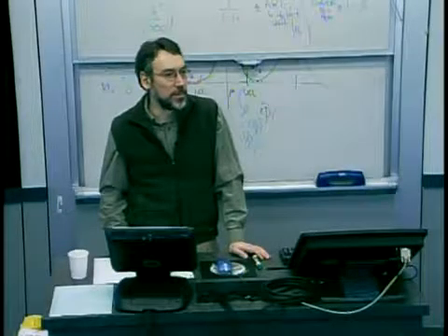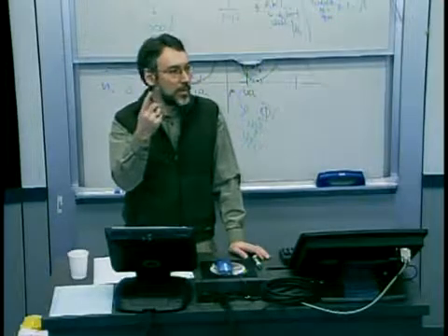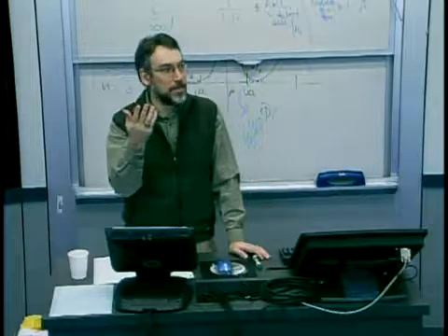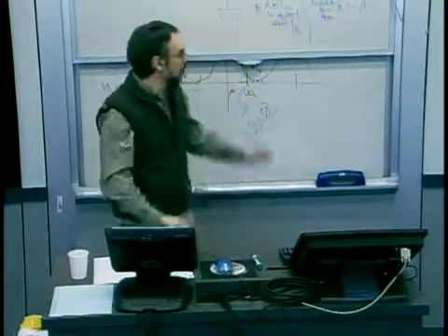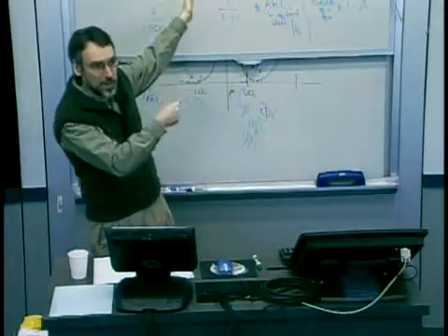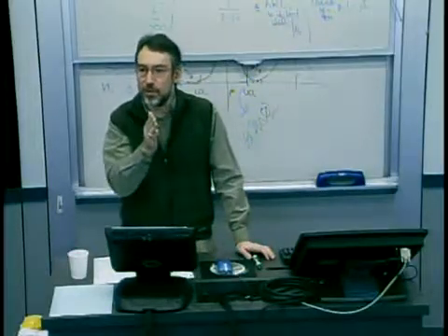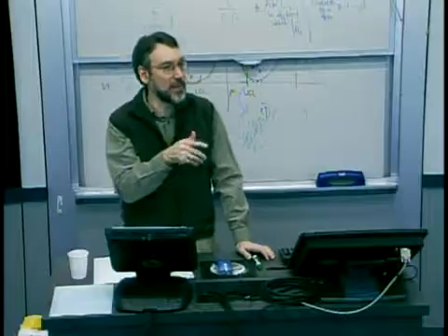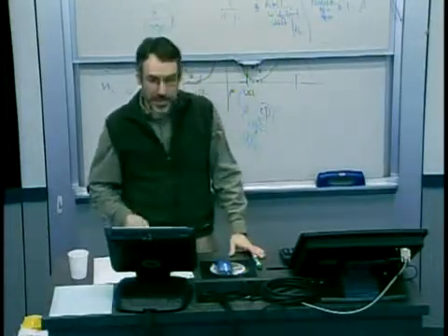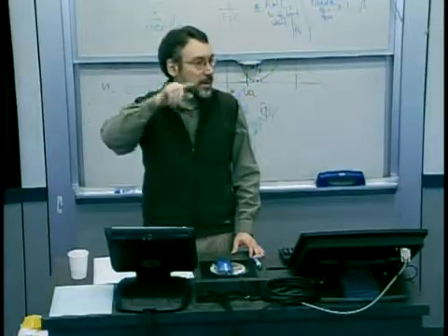What's another thing you might do? Do you look just at that one single point? What other data do you have? You can look at the trends, so like Western Electric. Exactly. So now you can look back at the control chart data that has been plotted either manually in old systems or in the computer system. Track back historically and start to look, is there some other evidence that wasn't triggering an alarm, but that might give you a sense? And a telltale one might be, in fact, a slow drift in the points.